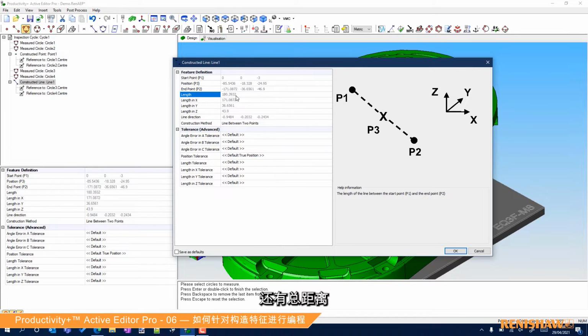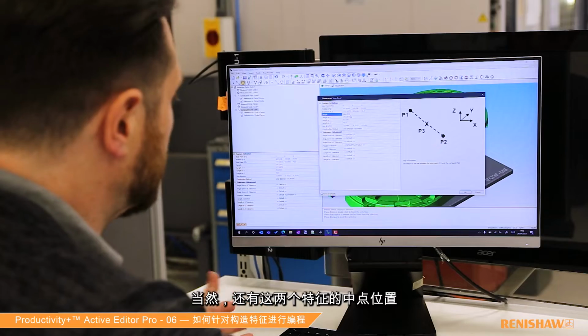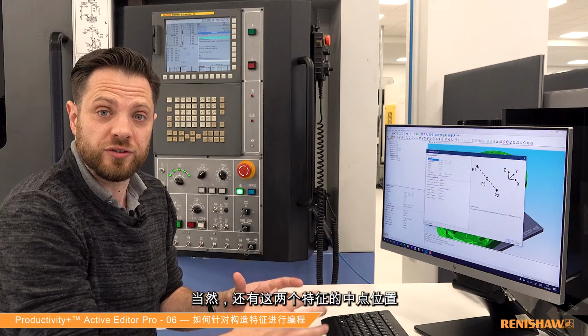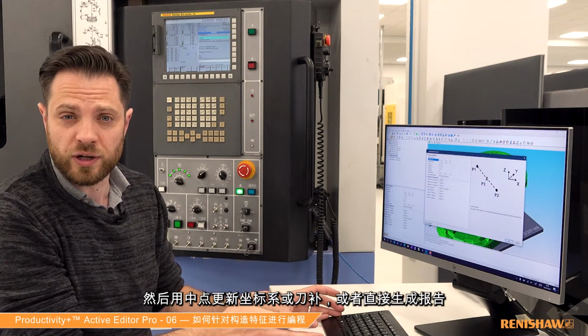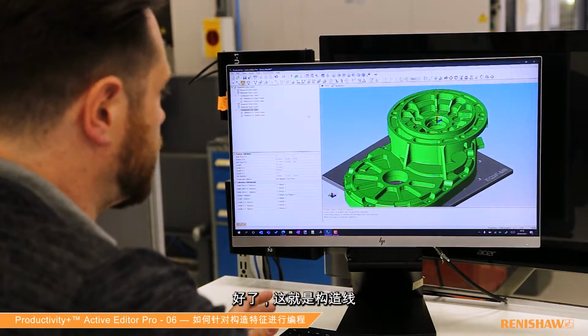We do also have the total distance, which is the shortest distance from the center point of both of those as well. And of course, it will give us a midpoint position of those two features. So again, if you wanted to measure two features, find the midpoint and use that to update a coordinate system or a tool offset or just report on it, this is how you would do it. Okay, so that's the constructed line.